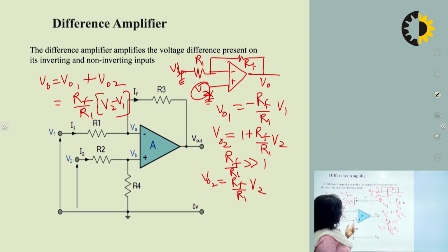Now this signal has been further modified. Here also we are having a voltage divider network at the non-inverting terminal. If you compare this circuit and this circuit, we can see that this is an additional circuit. This circuit can be simplified very easily by using the voltage divider theorem. To make this circuit equivalent to this circuit, we will be trying to find out the voltage across VB.